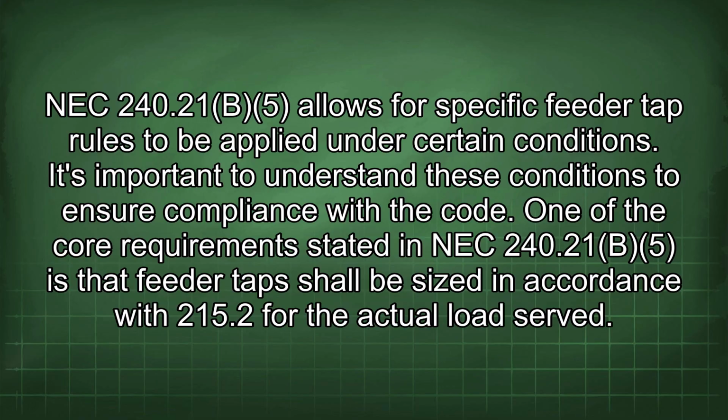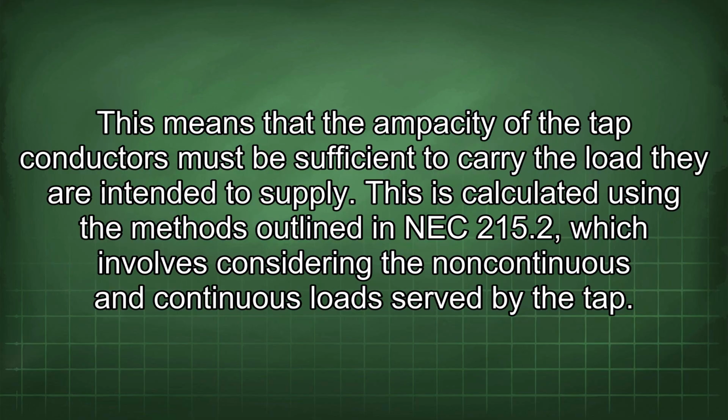One of the core requirements stated in NEC 240.21(B)(5) is that feeder taps shall be sized in accordance with 215.2 for the actual load served. This means that the ampacity of the tap conductors must be sufficient to carry the load they are intended to supply. This is calculated using the methods outlined in NEC 215.2, which involves considering the non-continuous and continuous loads served